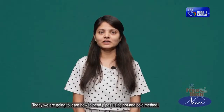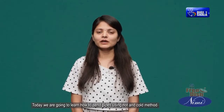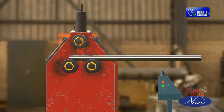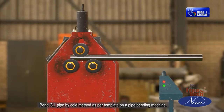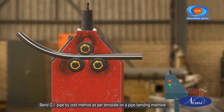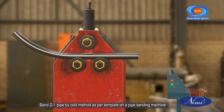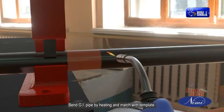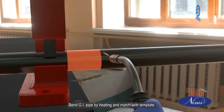Today, we are going to learn how to bend pipes using the hot and cold method. At the end of this demonstration, you will be able to bend GI pipe by cold method as per template on a pipe bending machine. Bend GI pipe by heating and match with template.